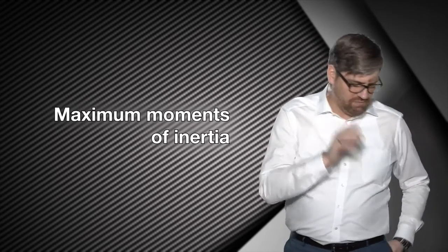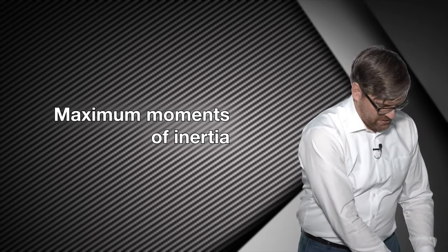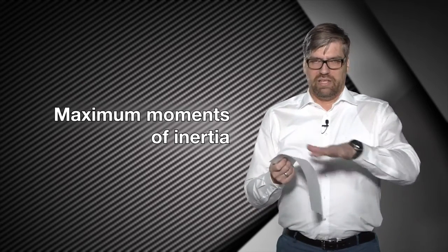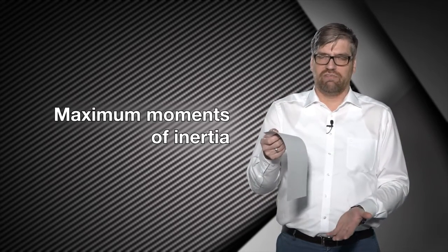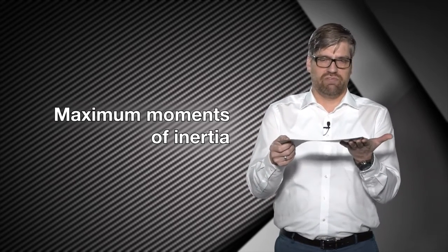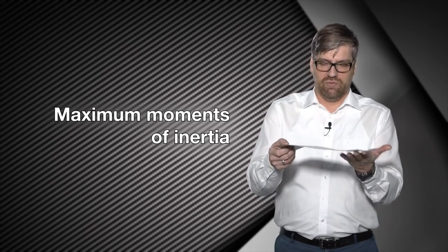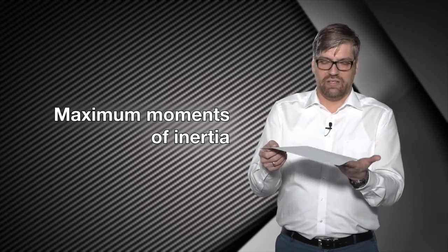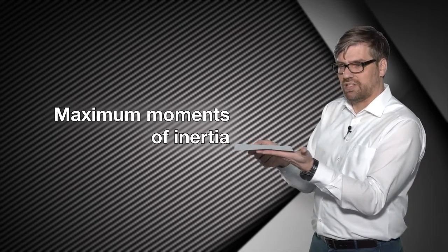Also, design large moments of inertia. What does it mean? Well, I can again show you on this simple example of a sheet of paper. Take this plain sheet of paper, and this should carry its own weight, and you will see that it fails. We have a very, very large deformation, and when you think, well, this should be a ceiling, a floor ceiling or something like that, you will see, well, you can't use this, so the structure fails, even carrying its own weight. And this is because the second moment of inertia is rather small, because the thickness is rather small.